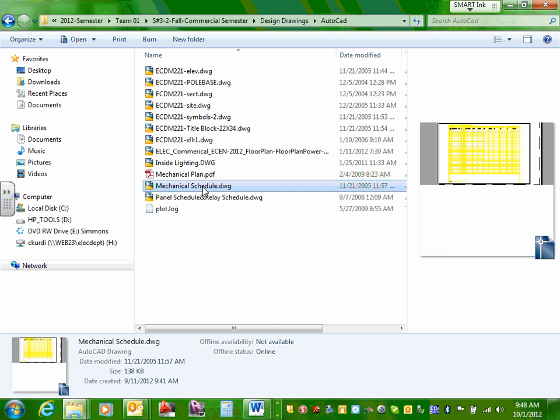So if we have a receptacle there, after I drop it in the wall and I circuit it, you have to learn first how to find it, second to drop it in the wall, third to circuit it, fourth you need to tag it. They call it a tag. You're going to assign a tag right next to it, writing RP for receptacle panel, dash C5. So that will be receptacle panel circuit number 5. That's called a tag. So really, for the most part, you're going to enjoy the power. It's really cool. There's not a whole lot to it, but there are tweaky things you have to learn.